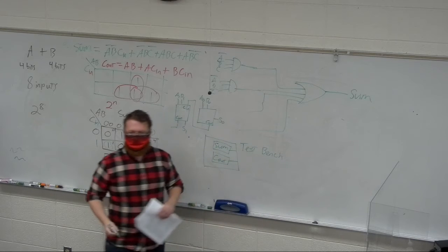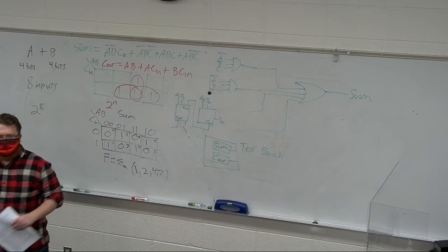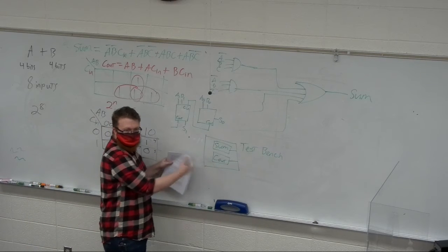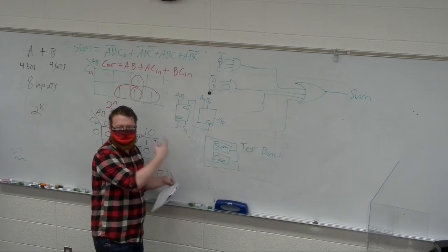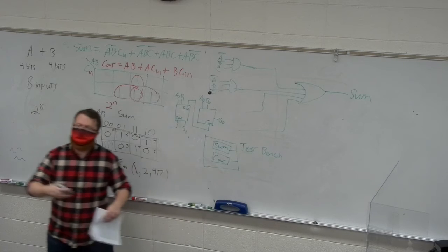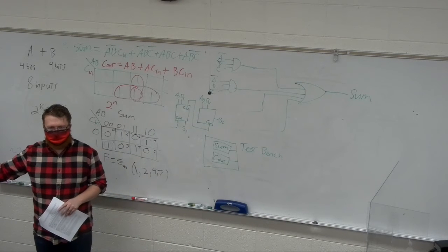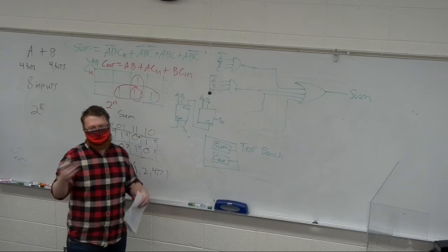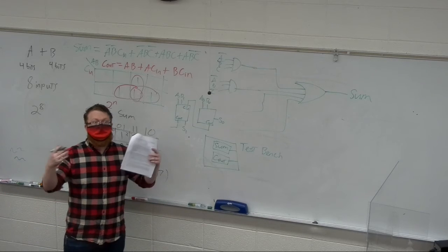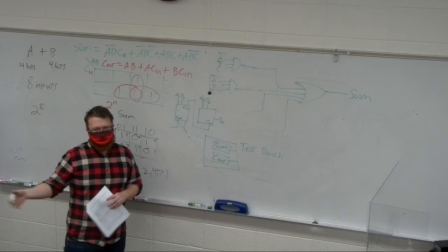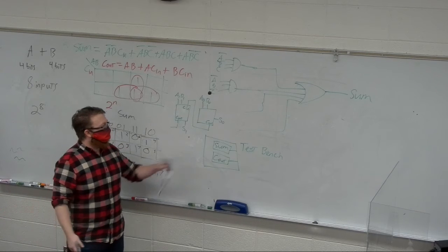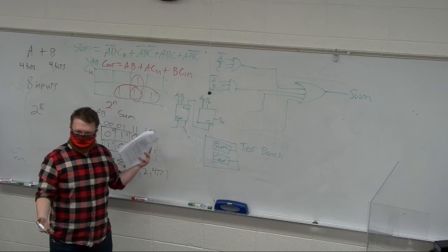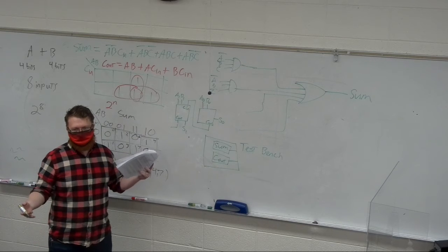We will eventually learn how to design a test bench. What a test bench does is it takes this black box and it sits and throws inputs at it. You tell it what inputs to throw at it, and then it reports what those outputs are. And you know what the output should be based on the input, so then you can do some evaluation, say, this is working as a 1-bit full adder. And if this works as a 1-bit full adder, then when I start sticking them together, it should work as an n-bit ripple adder.